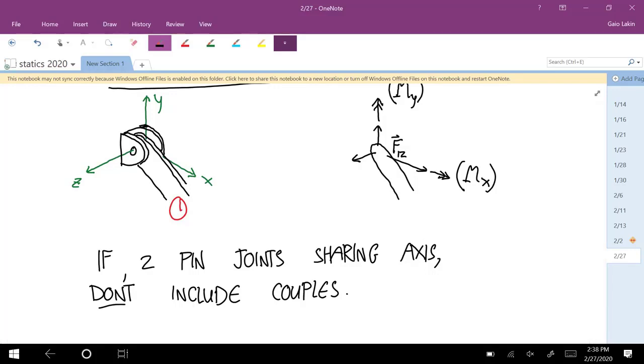So you're going to have to do problems where it's not the z-axis that the pin can rotate around. You're just going to have to visualize it in each individual problem. How does this thing rotate? This might be the x-axis in some problems, or the y-axis in some problems. So you just have to be able to visualize how the degrees of freedom are restricted by the joint. Find the places where it can't translate or it can't rotate. That's where the loads are applied. Okay?